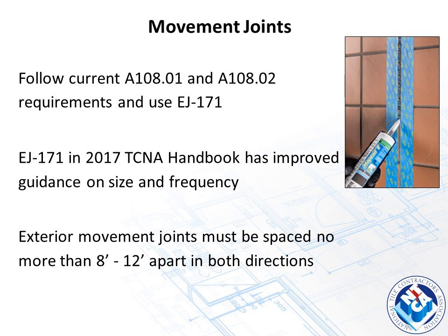And I'll also mention movement joints need to be properly installed. What I mean by that is if this joint right here is, let me grab its pointer, I'm sorry. If this joint is filled 7/8 of the depth with mortar and not open, that installation is not going to expand and contract regardless of how flexible this sealant is that's installed over the top of it. And I see that frequently. So these joints should be open as much as feasibly possible, certainly the depth of the tile, and filled with sealant over a backer rod.